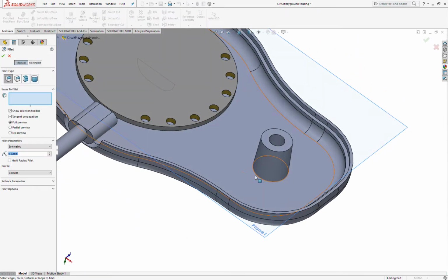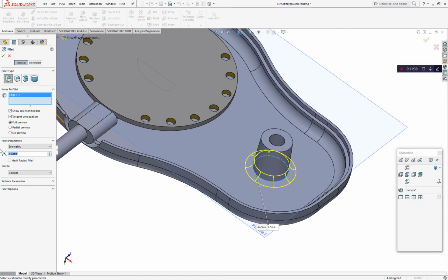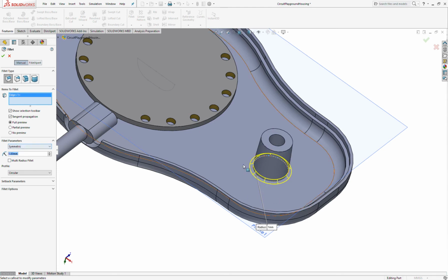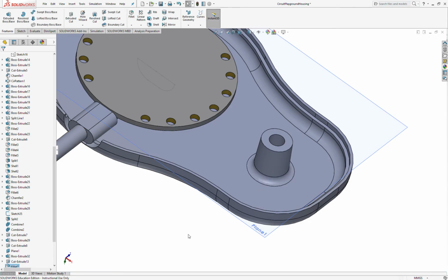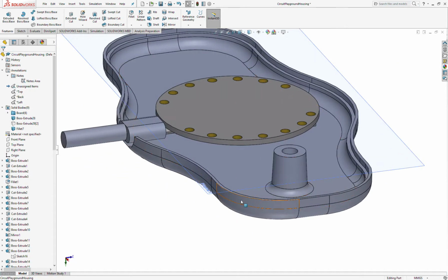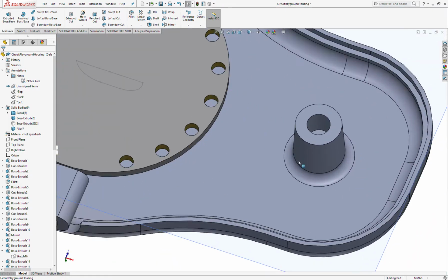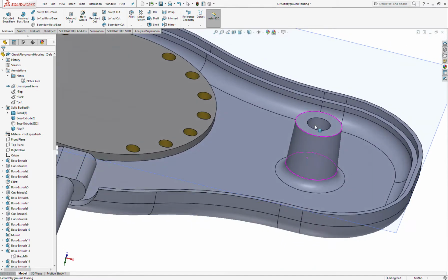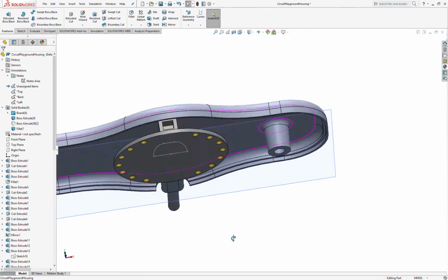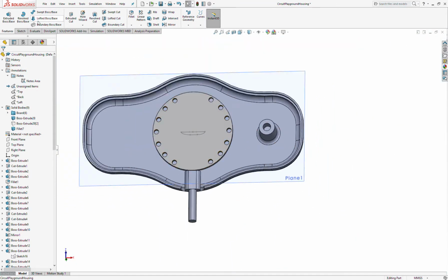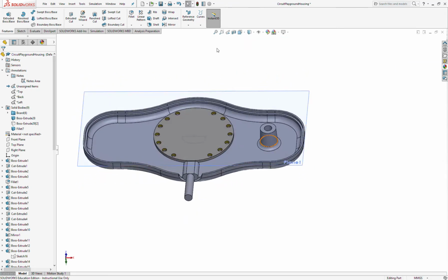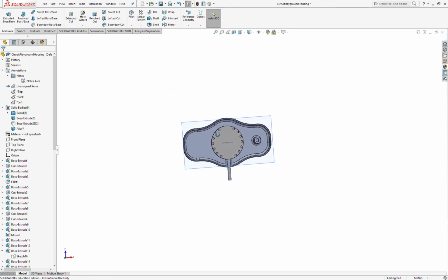One of the key things to do with these is to add a reasonable, not necessarily super huge, fillet around the edge. It helps make a slightly better bond there and will help that part from fraying off. We can also add some triangular support ribs that come off. I'm not really going to for this one. I may do some ribs on the bottom though. So we've got that. So that's half of this equation.